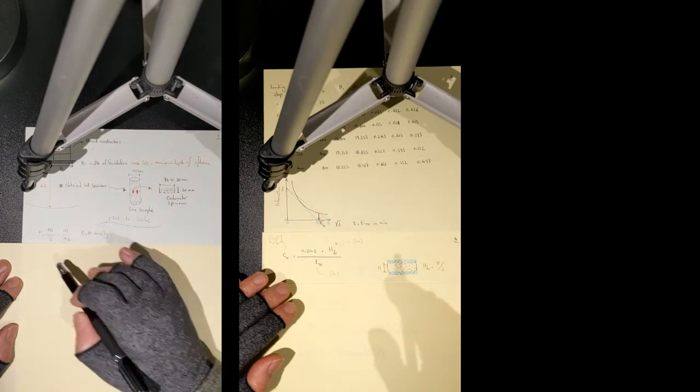And M is the mass of the soil sample. Obviously, you need to take off the wax, weigh it, and measure the M. Bulk density is M divided by V. V is volume, and since you are dealing with a cylinder, your volume is equal to A, the cross-sectional area of your cylinder, multiplied by H, the height of your cylinder. So bulk density can be easily determined. Now, if you have the bulk density, then you have the unit weight. Bulk density multiplied by g, gravity acceleration, is unit weight.